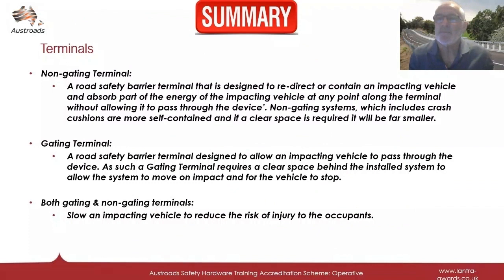So in summary, non-gating terminal: a road safety barrier terminal that is designed to redirect or contain an impacting vehicle and absorb part of the energy of the impacting vehicle at any point along the terminal without allowing it to pass through the device. Non-gating systems, which include crash cushions, are more self-contained, and if a clear space is required, it will be far smaller.